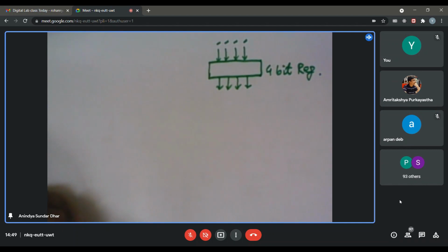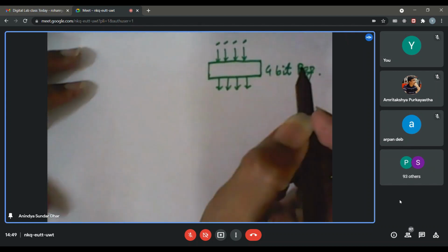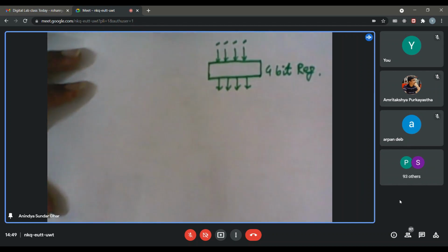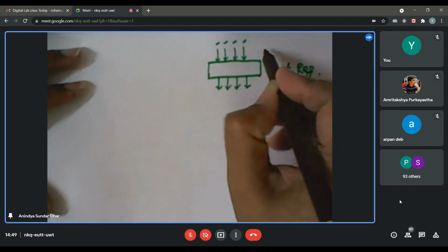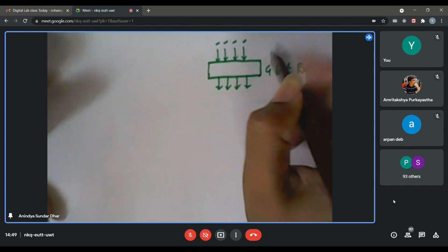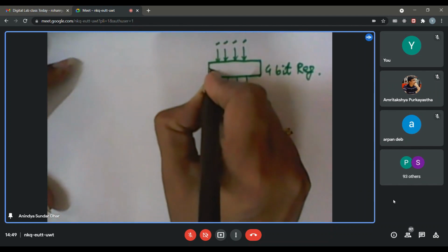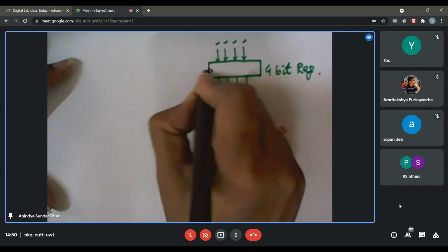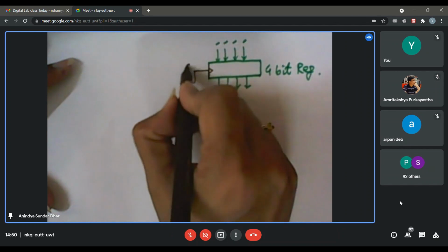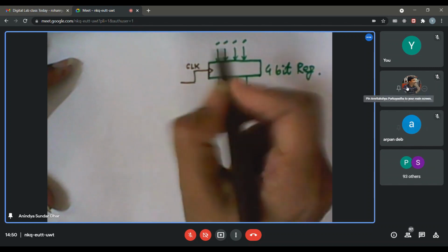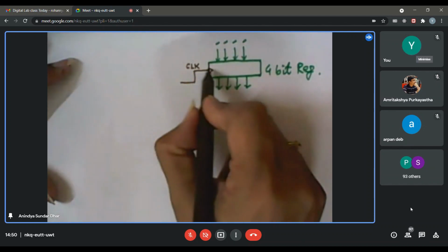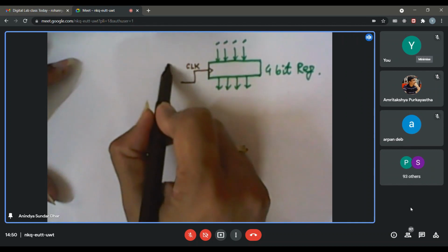Generally, there is something called a clock signal to a register, or in some cases there might be a latch signal or load signal, whatever way you say. So today, actually, we would introduce a so-called register which is edge triggered, a positive edge triggered. So you will find that here on this side they are showing it something like this. They say that, okay, it's a clock line. So using this clock, if we put this type of small triangle, it means it is sensitive to the edge signal, and in particular a rising edge of a clock.